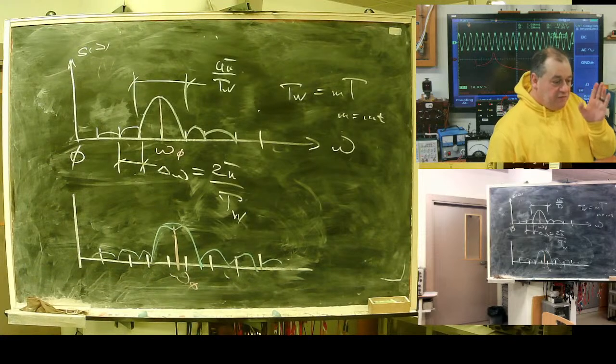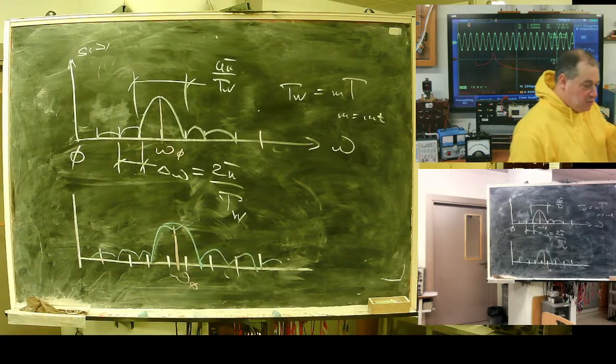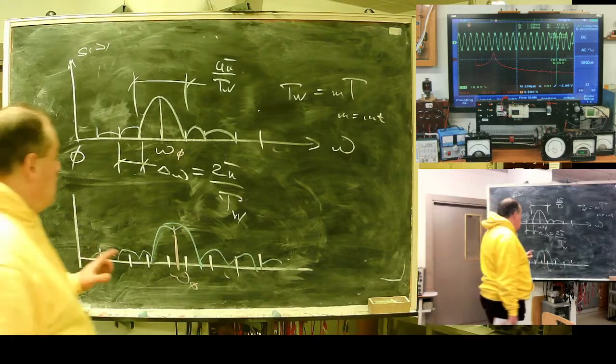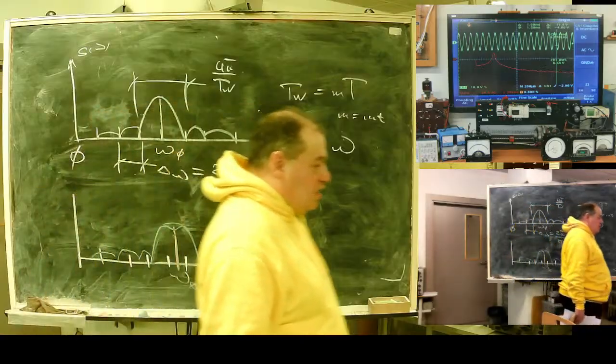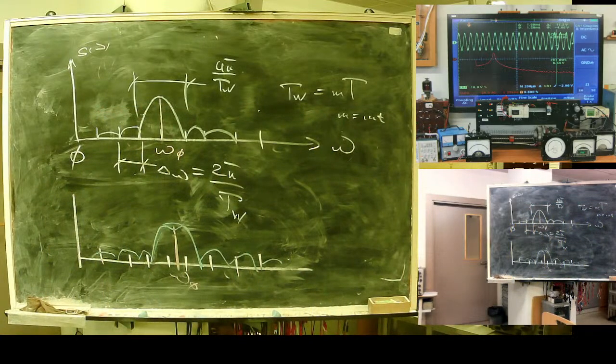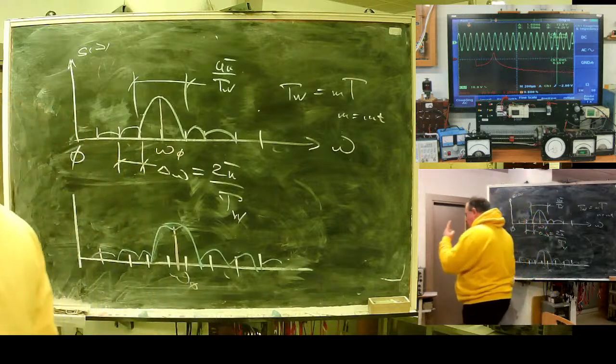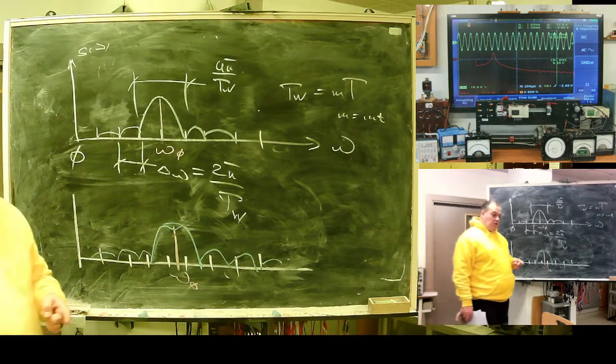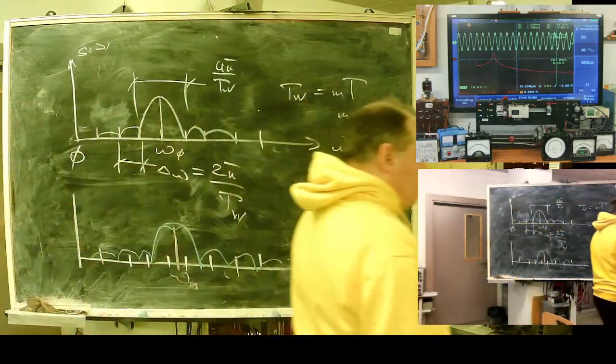Where is the root of this behavior? We observe a limited slice or cutoff of our original signal. This deformation is a result of what? Of convolution with a window function. In case we have a pure one-harmonic, one-frequency signal, the thing we observe is nothing else than a spectral or frequency representation of the windowing function.